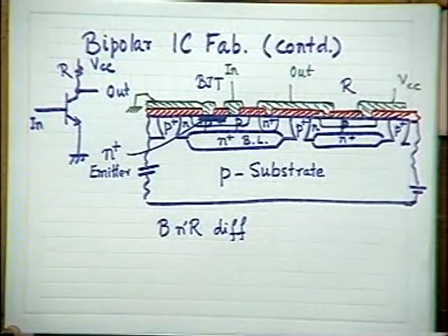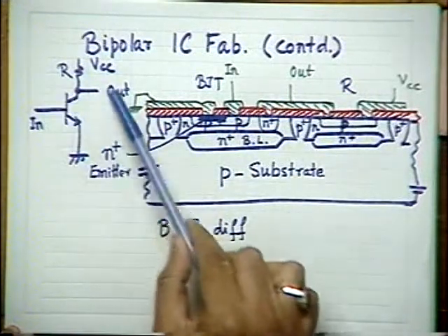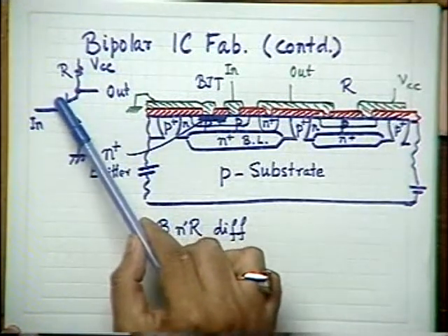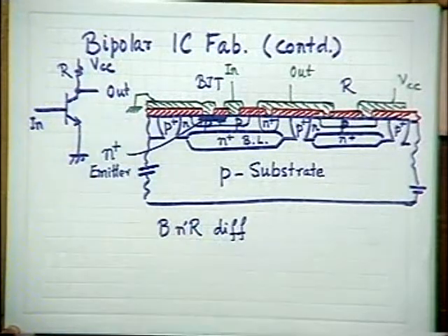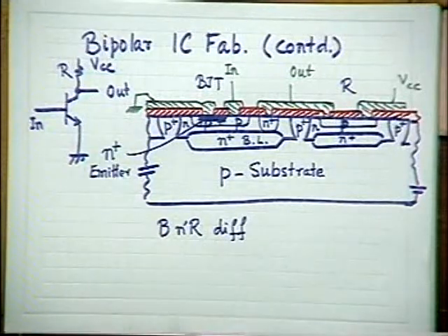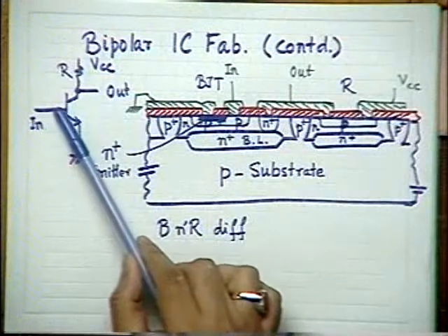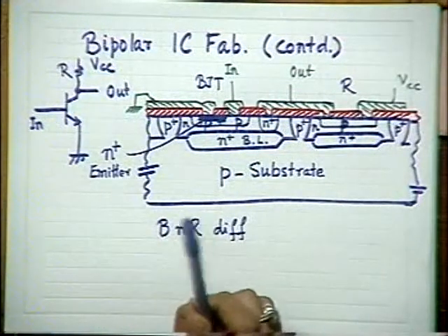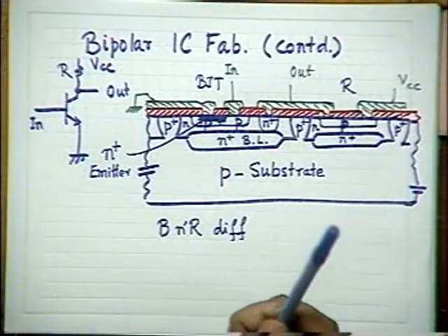And this is the basic thing in a bipolar IC. Please remember, this is a basic thing in a bipolar IC. It can be used as a switch. It can be used as an amplifier stage. Only for amplifier stage, I have to have a better arrangement for biasing circuit, which is not there at all here. We are not bothered about the temperature stability, etc. in digital techniques.